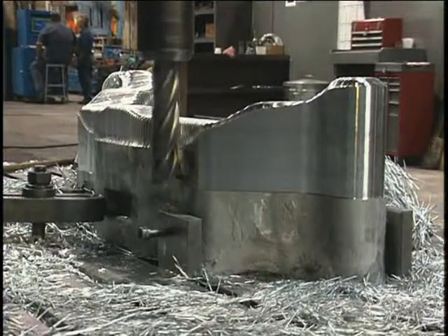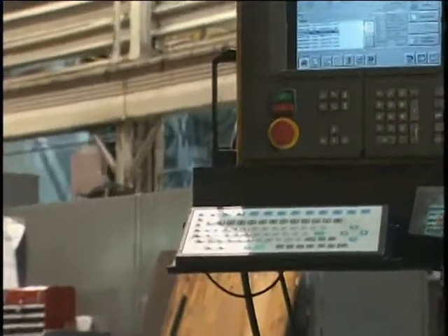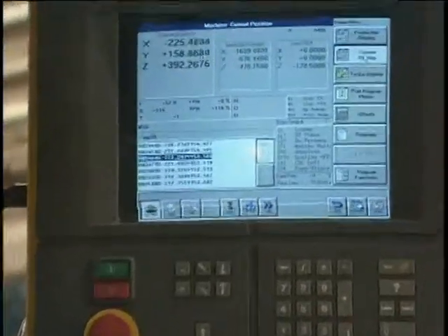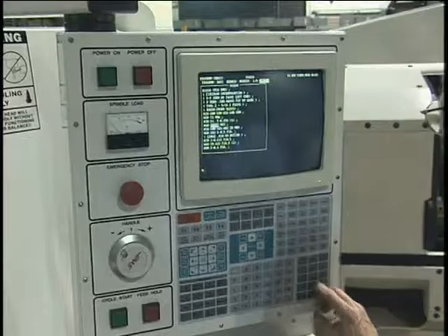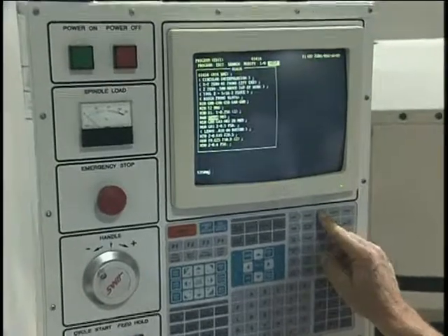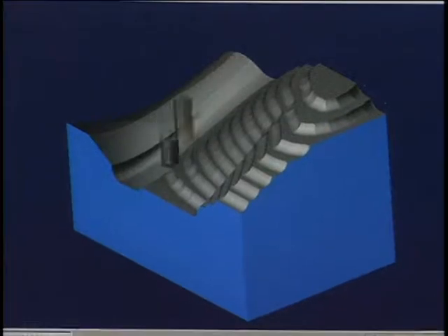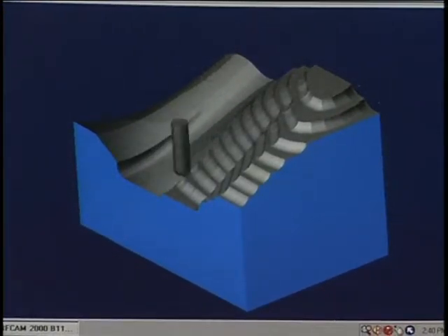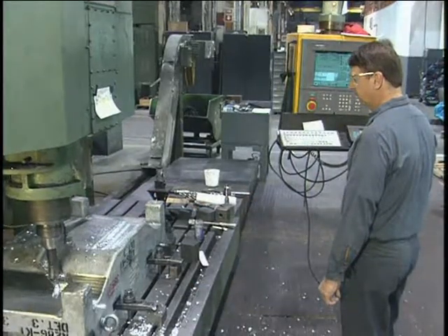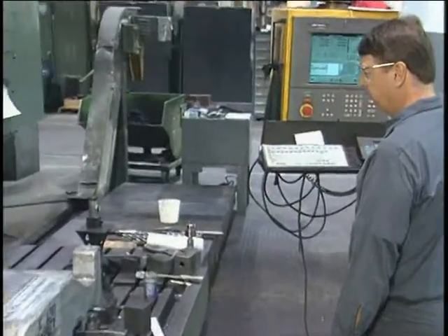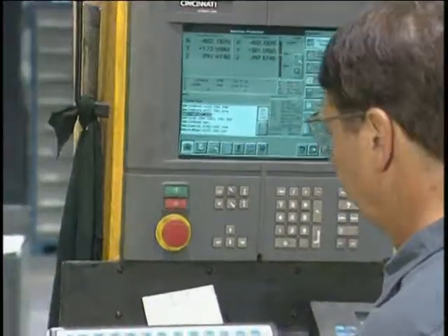All computer numerically controlled machining begins with a part program. A part program consists of sequential instructions or coded commands that direct the machining of the part. Part programs are primarily generated by either manual programming of commands or, more commonly, by the use of computer-aided part programming systems. To understand how computer numerical programming works, first requires a basic understanding of key computer numerical control principles.